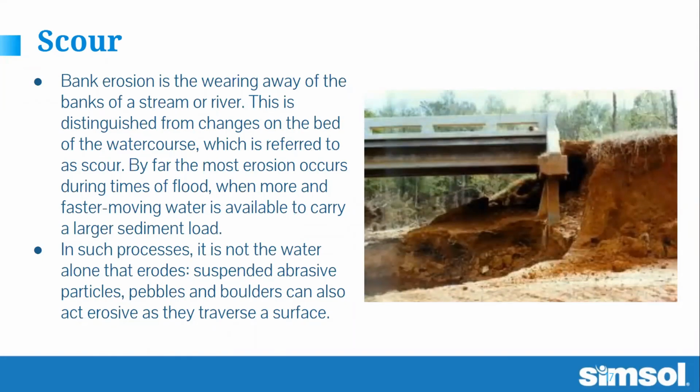Now, when we talk scour, you can see in the photograph here, this is bank erosion wearing away. The water in the river comes up, or the wave action working around the corner of a building is going to dig in and erode the soil. You see a lot of this, particularly in rivers, where the deeper holes are on the outside of the curve, where the water speeds up. And the inside of the curve is typically the sandbar areas where you camp, because as the water slows down, it drops all the sediment load and creates a sandbar.